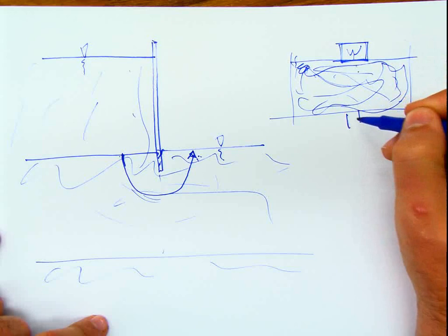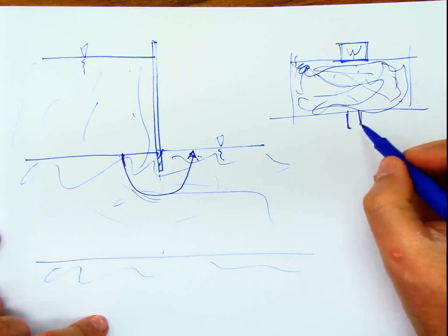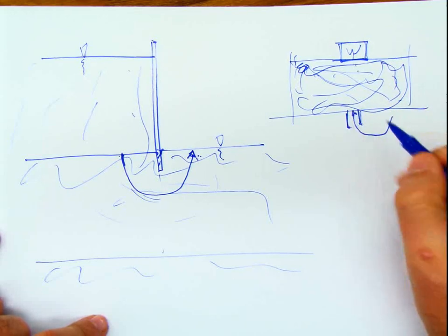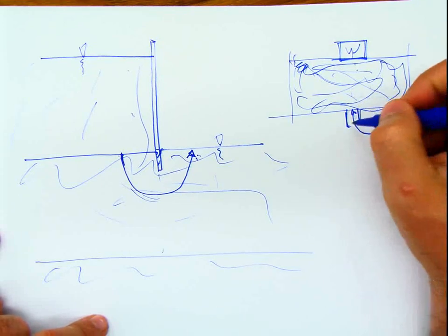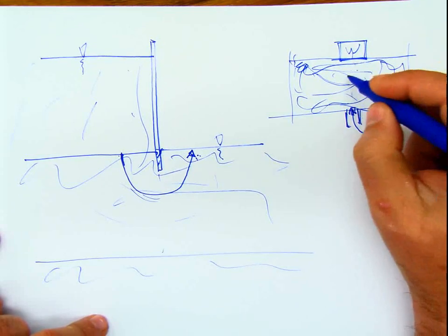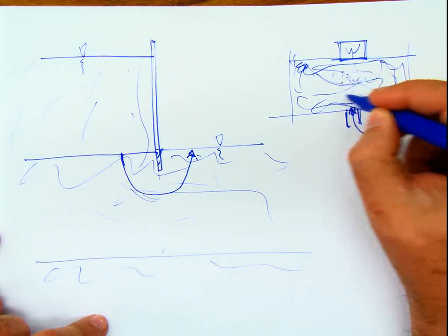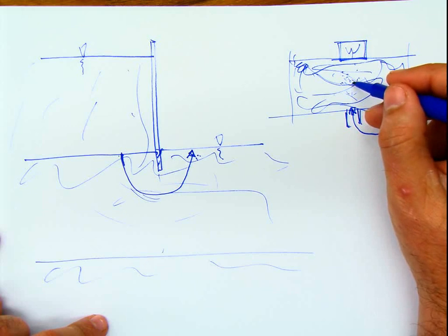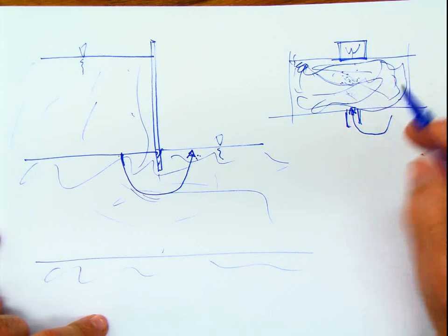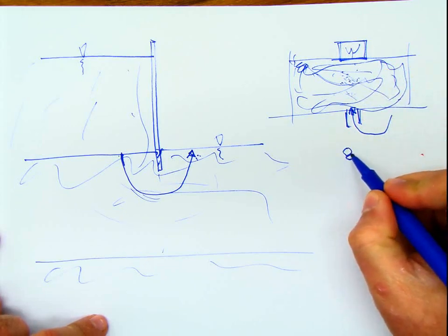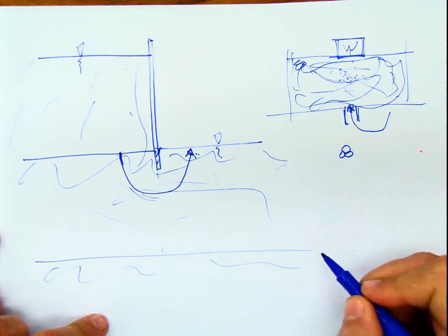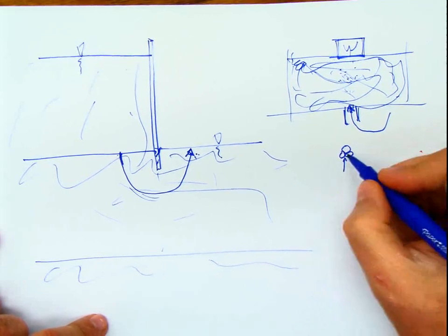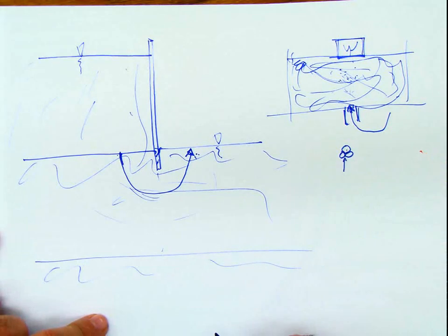Now, if you connect a hose here, a valve, and you start injecting water up, that water is acting against those intergranular pressures in the grains, and it's relieving the friction in between the grains. Imagine that you have 2 or 3 grains in contact here, and suddenly you are shooting water. The friction between these grains is lost, or is going to become lost.